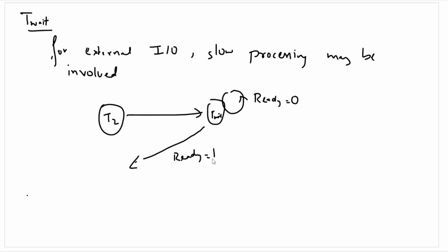The microprocessor will continue to remain in this state, and only upon successful execution will it come out of this T wait state by checking the ready signal. And during this time all the buses basically are kept on hold. Only the data bus is waiting for the data.